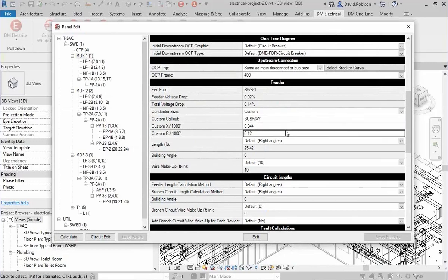So we're not going to use any sort of description. You also need to tell us the impedance values. That's important for doing our calculations. And at this point, we don't know because you've just typed in something custom. So we need to know what those impedance values are. So typically you'll get some manufacturer data from the busway, or you happen to know what those wires are. So you'll have to go to your NEC and look up the appropriate values, taking into account all the stuff going on. But type in those values, and then we'll use that for all of our calculation purposes.